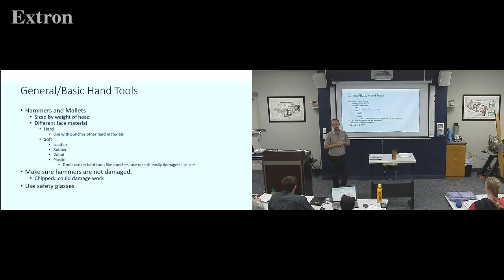It's in AC 43.13 under inspections, section 11, towards the back, like third page over. Anyway. You're talking about that scope thing that can check to see if there's a crack? Yes, but it's not eddy. It's the other one. Ultrasonic. Thank you. Ultrasonic inspection. So it sends a sound wave through it. Yeah. I doubt there's any radiography done anymore. Good. It is actually in AC 43.13, radiography.